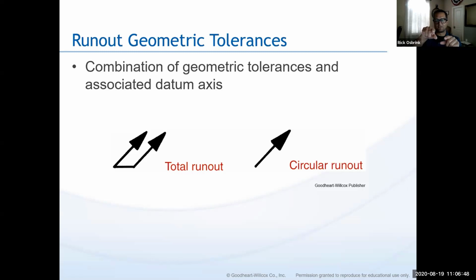Ideally we want that cylinder to be perfectly cylindrical, to where it doesn't jump around like this. We want it to spin perfectly true with the axis of the lathe. Well, that's not always the case. There's always going to be something that we call runout, and I'm going to talk about runout when we talk about the lathe as well. That is basically this out-of-round, and it might not be your part, it might be the chuck, but it could be your part.